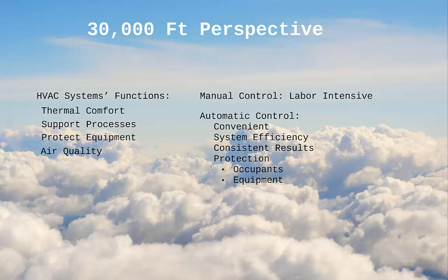Think of the control of fire dampers to starve a fire of oxygen, or chillers turning off to prevent a coil freeze-up when it realizes low pressure in the refrigerant. I would prefer an automatic control system handle these tasks, as I may not be present or conscious to activate such dampers during a fire, nor is my pressure sensing skills on par with that of the sensors those chillers come equipped with.